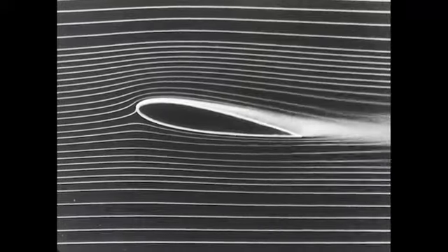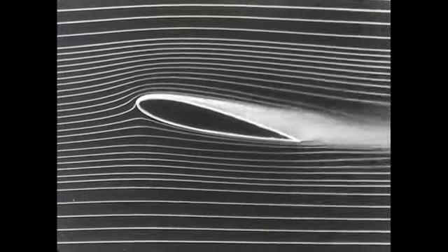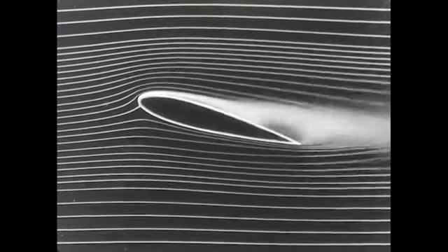In the diffuser, the turbulent boundary layer along the bottom wall does not separate, while the laminar one does, because the three-dimensional interchange between regions of high and low momentum fluid in the turbulent layer is more effective than the molecular diffusion in the laminar layer. Similarly, a turbulent boundary layer on the upper surface of this airfoil prevents large-scale separation or stall until a very high angle of attack.